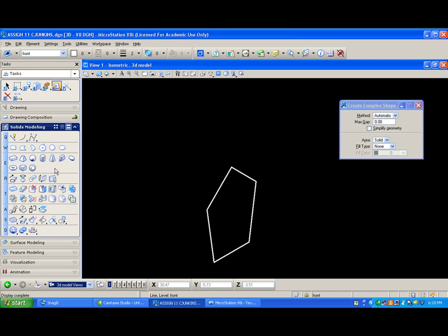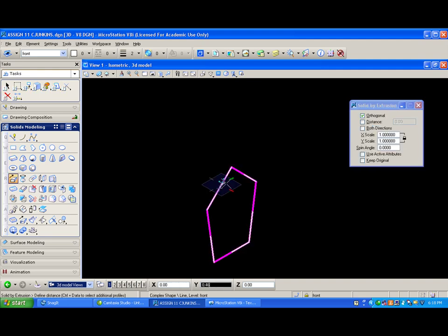We're going to extrude this now using the solid by extrusion tool. We just want to left click on our object. Still thinking here, I guess. There we go. And we're just going to pull this out. We're going to use some 3/4 inch wood to build this. Actually, let's go 5/8. That's a little too thick for a birdhouse. So just key in 5/8, and there's the thickness of the front panel.